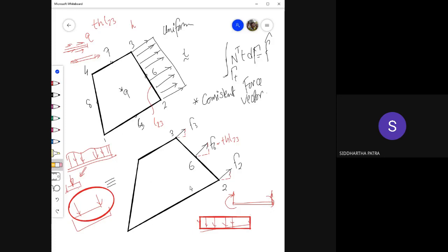Okay, but there is one thing to say here. Firstly, the deformation is under consideration, and the third thing is, here we are talking in terms of finite element method, where we are using a numerical method and we integrate the traction over the geometry to get a force vector. Okay, and you probably have done some analysis with the four noded quad element where you are supposed to get the force vector from the traction.